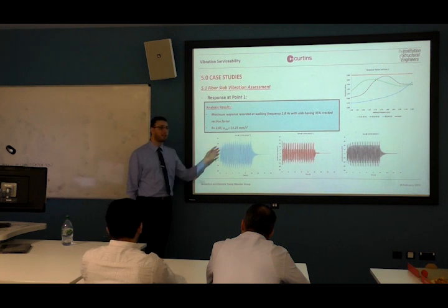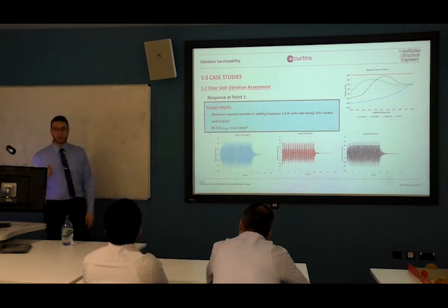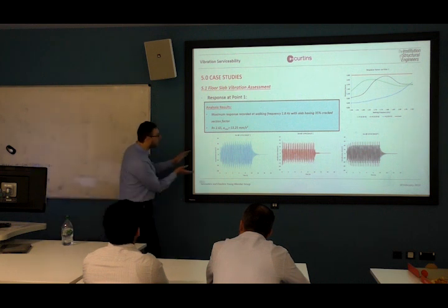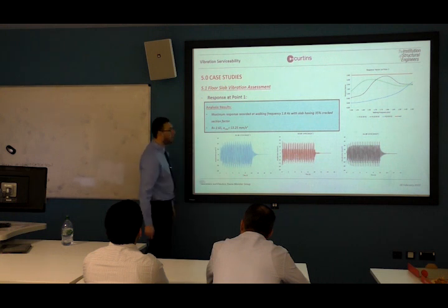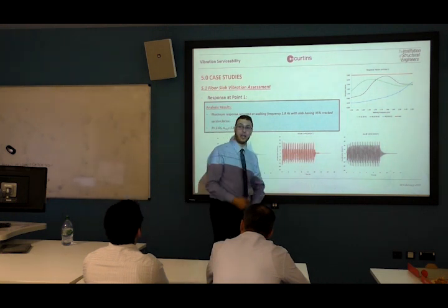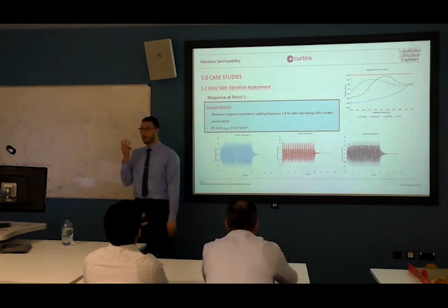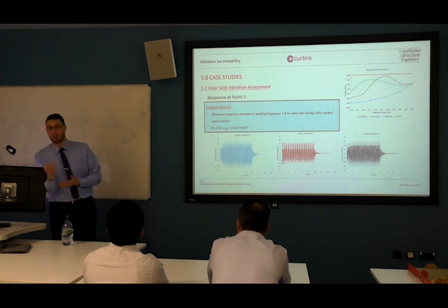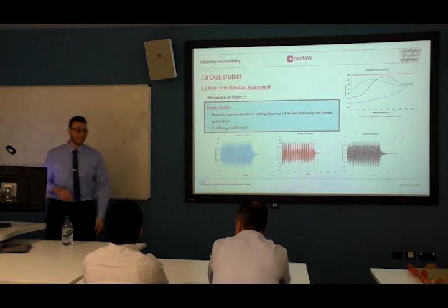So 1.5 was giving me some resonance for the 4th harmonic. So you can see some nice resonance build up here. 1.8 is not actually a multiplication for any harmonic, so no resonance. 2 for the 3rd harmonic, 2 times 3 is 6. So no resonance there.